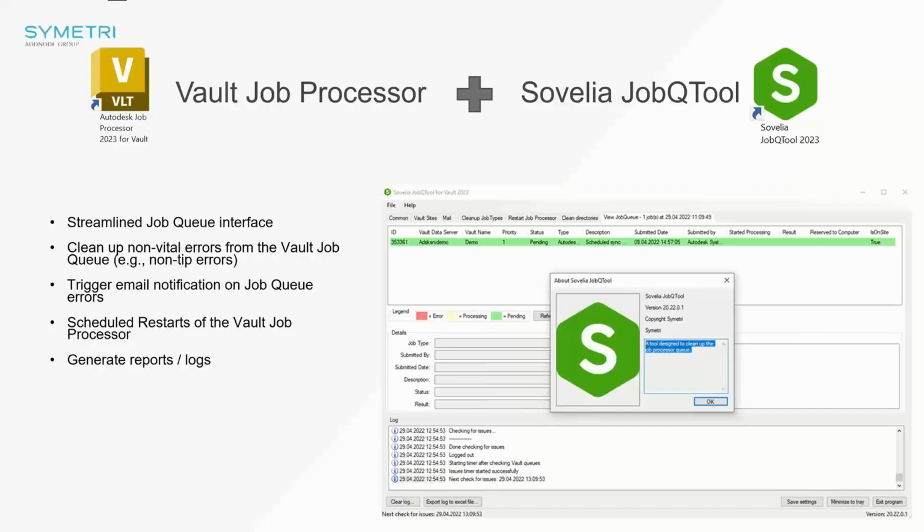On top of that, we have trigger email notifications from the job queue. You could set it up so that if errors appear in the job queue, some Vault administrator is sent an email notification to say the following error appeared in the job queue, and they're prompted to go into the job queue and check those errors. This is quite useful because if you're a Vault administrator, you'll know that keeping an eye on the job queue is a manual task, or has been historically.